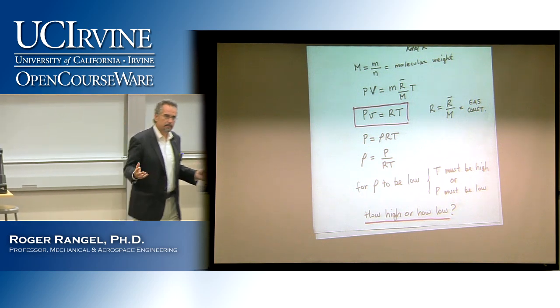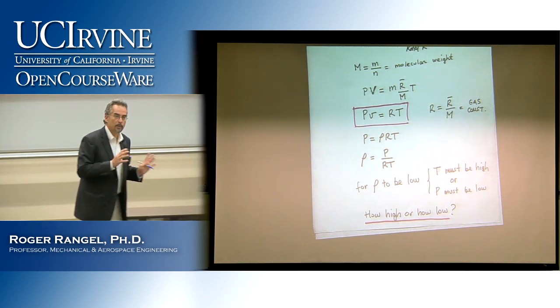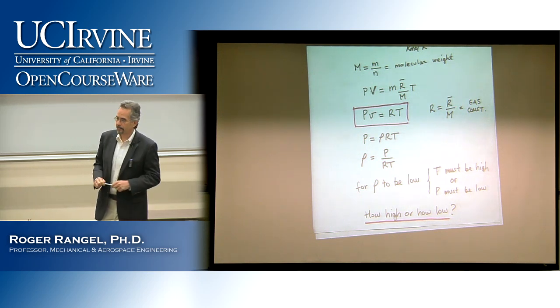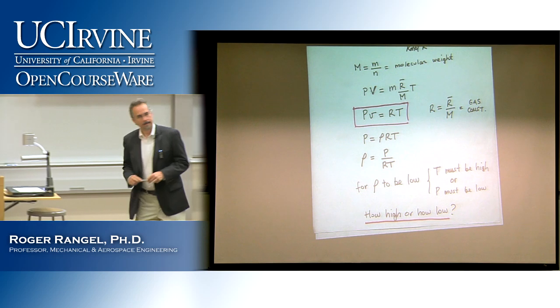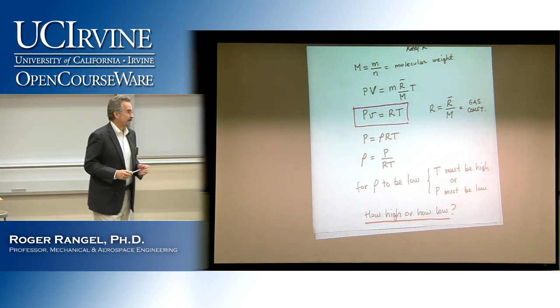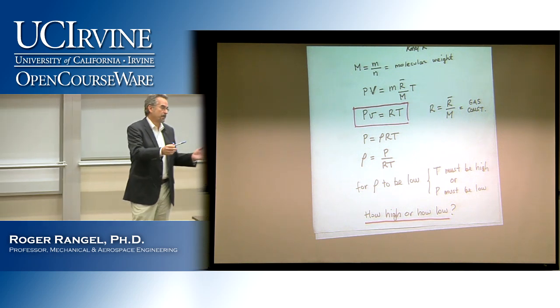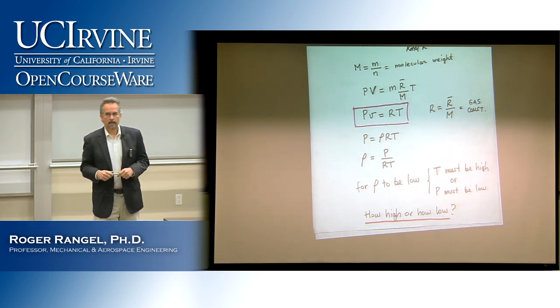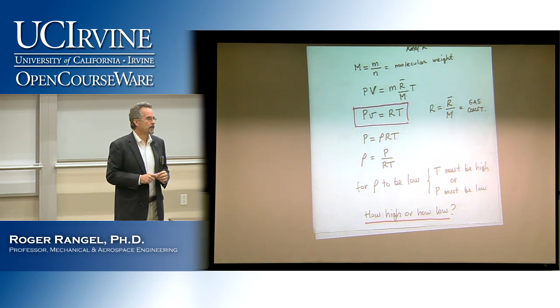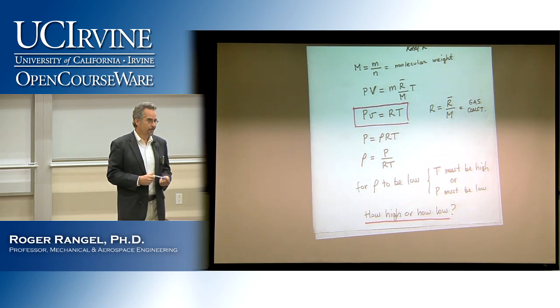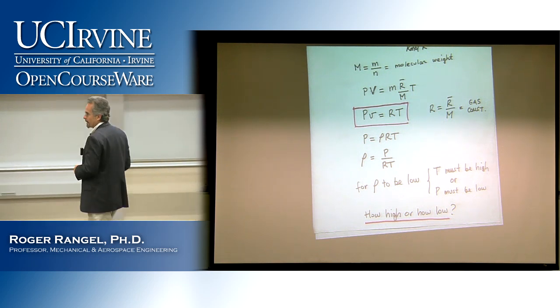If I happen to have a table for that substance, that will always be the most accurate choice because the tables are accurate. Suppose you don't have the tables for that substance. For example, for air or nitrogen, since we were looking at nitrogen, there might be a table on nitrogen, but pick a substance that there is no table for. Then you have two options. Use the ideal gas law anyway, because you got nothing else, and maybe try to get an estimate of what the error might be, or do something better.